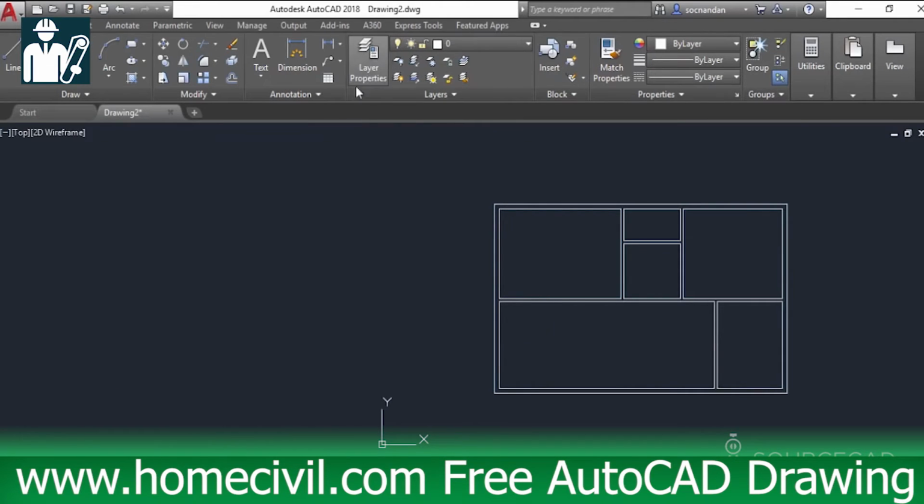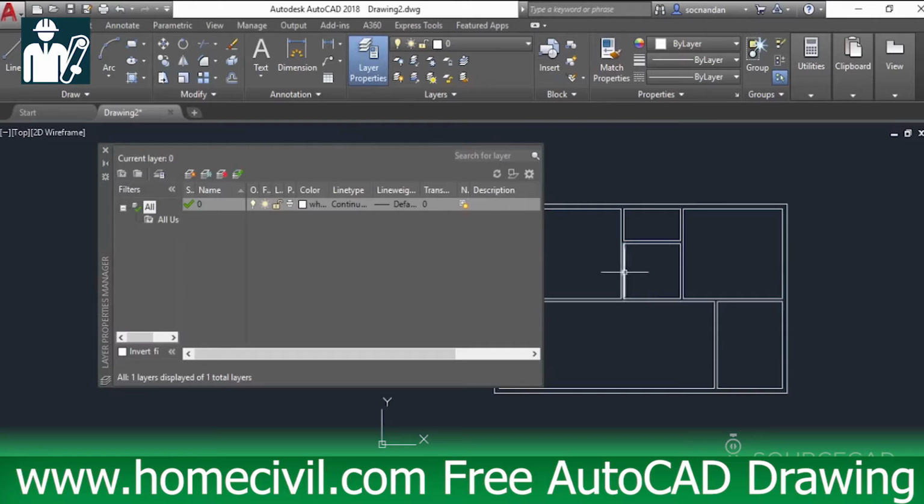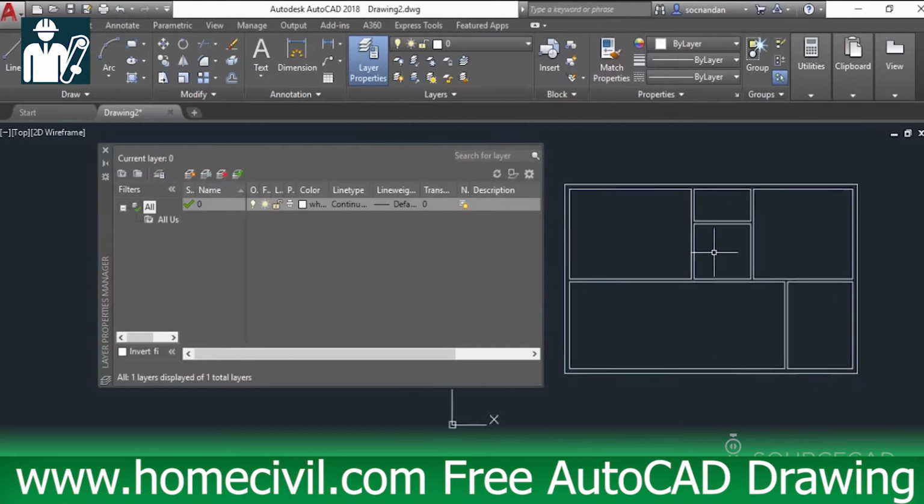Now click on this layer properties and add some layers to the drawing. We need to add these layers because we will place different objects on different layers for easy classification. That's the general way of making these drawings, and you should also try to put different kinds of objects on different layers.